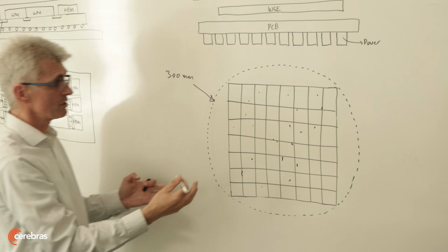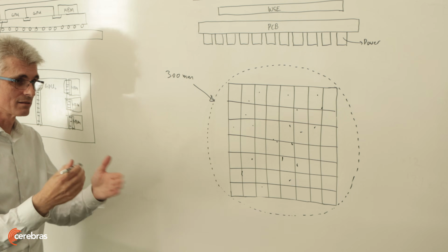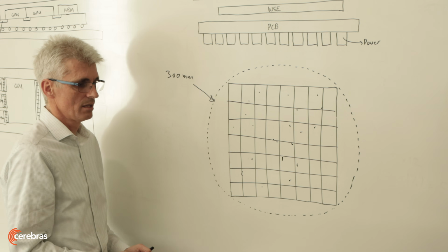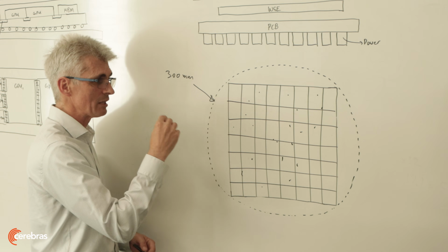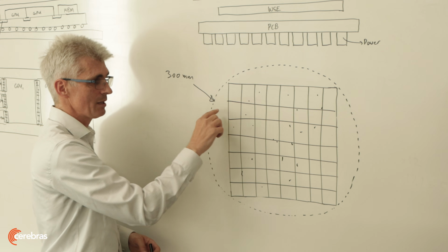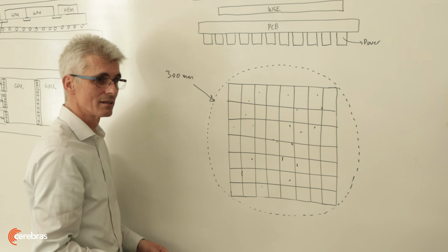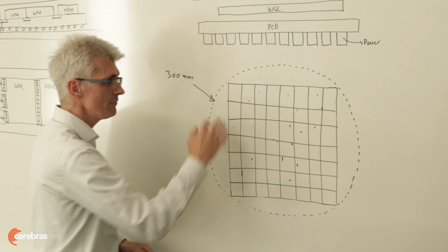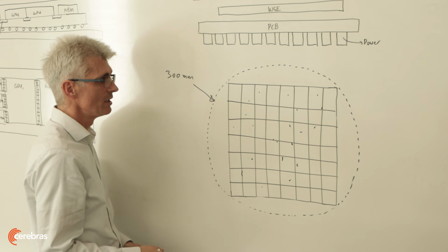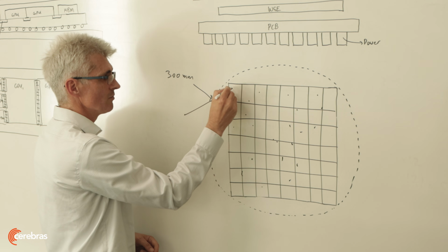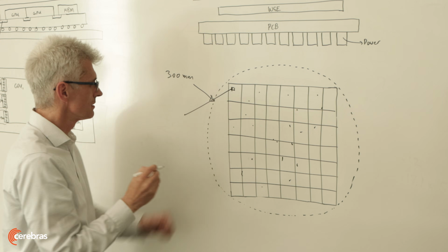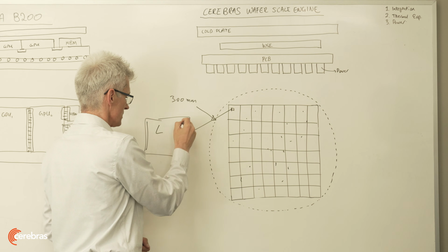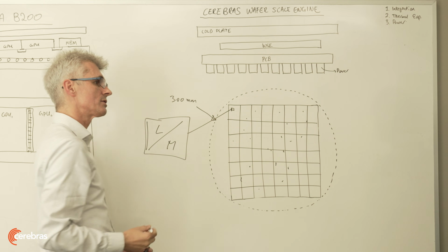Everyone designs chips with defects. SRAM, for example, can be designed with a little bit of redundancy so you can cope with defects. But if your entire logic design is capable of dealing with defects, then you could actually yield an entire wafer. If you have the entire wafer at your disposal, why not, in one area of a reticle, create a core that has both logic and memory very close to each other?